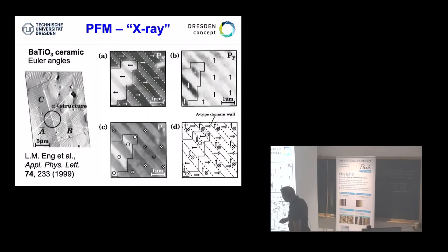And we zoom in on a small area like shown here, and do exactly this kind of X-ray or tomography along the PX, PY, and the PZ direction. And you can recombine. We also do a quantitative measurement in the sense that we calibrate that. We take barium titanate single crystals as a calibration, and so you know PX, PY, PZ quantitatively. You can combine this in a picture, and in the end, what comes out is clear that the grain you have chosen has a certain orientation with respect to an outer XYZ plane. These are the so-called famous Euler angles.